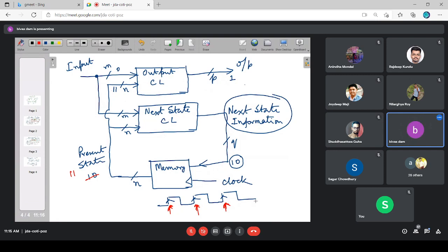That's all. Somebody may say that they are not happy with the rising edges and should work with the falling edge. Fine, no problem. You can work with the falling edges also. There, the arrival of the newer falling edges will indicate the arrival of the newer time instants or time ticks. Tick, T-I-C-K.